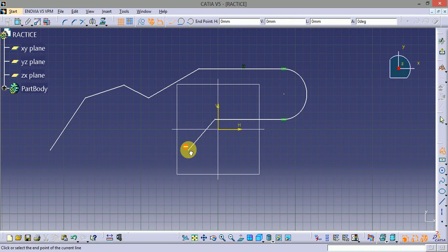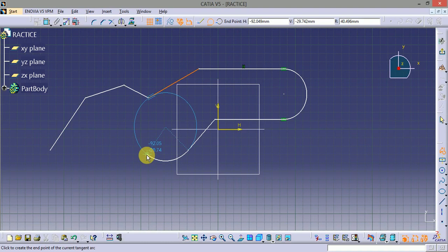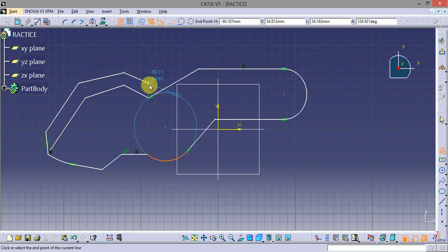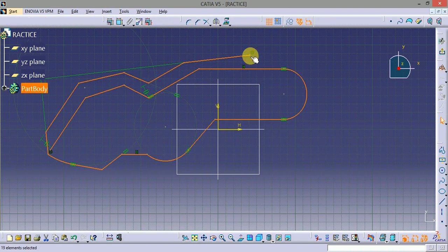Hold the mouse, and make the curve in downward direction, release the left click button, single click, then proceeding forward. Again I need to make a curve. Hold the mouse, make an invisible curve by your own, release the mouse, single click. If you need to get out of the command, double click, and you will be out of the command.